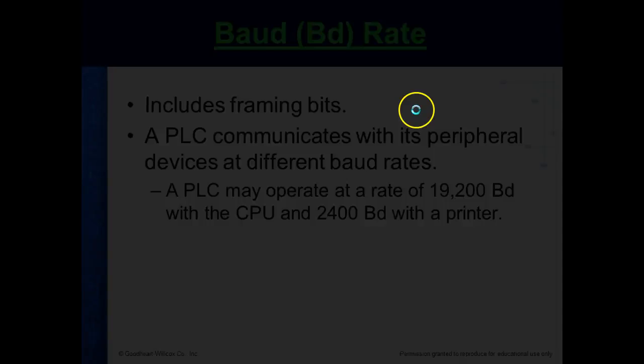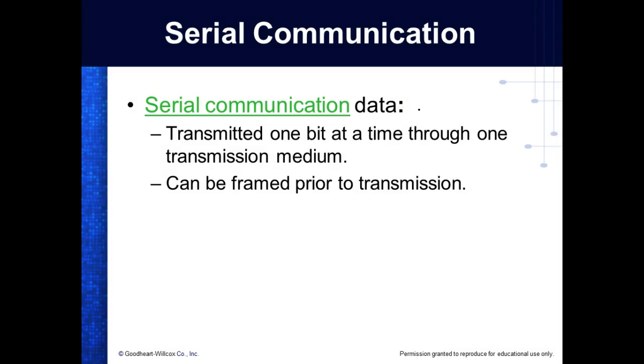Serial communication is by far the most widely used. Inside the processor, inside the PLC, most of your communication is parallel. Now, the advantage of parallel is really high speed, right? But I'm not dealing with high speed, right? We're dealing with things that, compared to a computer, you might see these cans flying by. To us, they look like a blur, but to a computer,